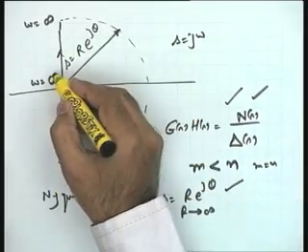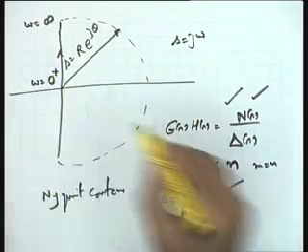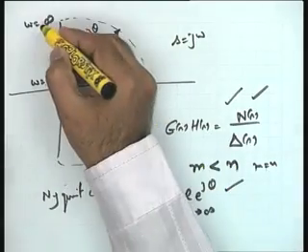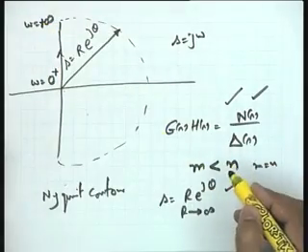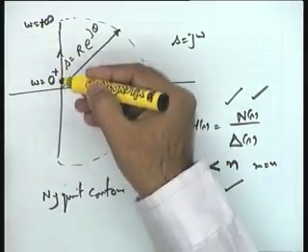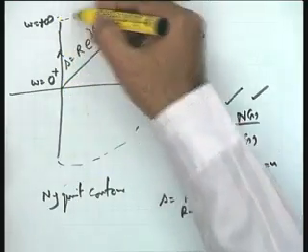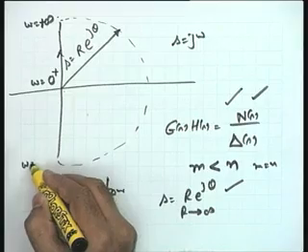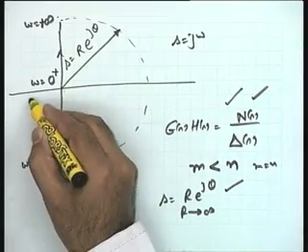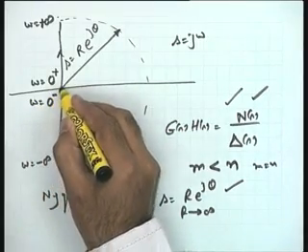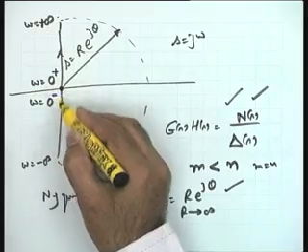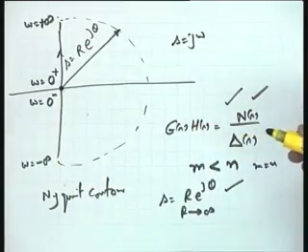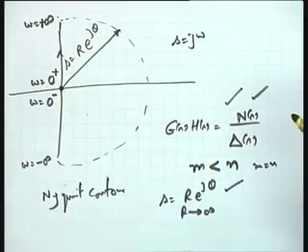I can take this as omega equal to 0 plus. This is omega equal to plus infinity. Just to identify various points, you come to this point through the infinite semicircle, call it omega equal to minus infinity, and this is omega equal to 0 minus. Omega 0 plus and 0 minus both join at the same point, which is the origin of the S plane.